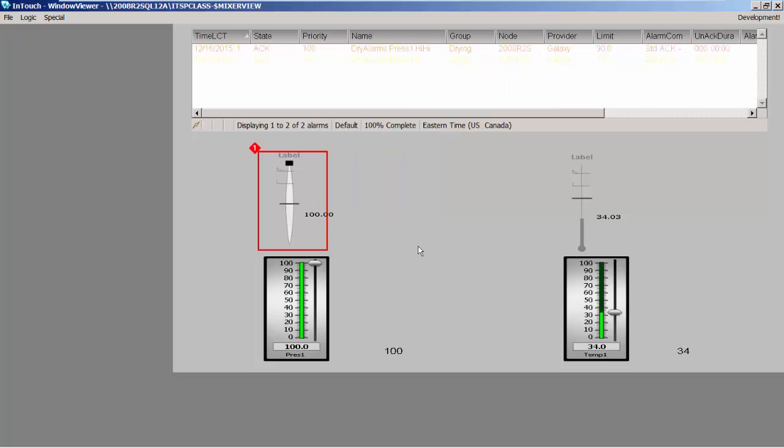And then you can see it stopped flashing, but it's showing me now that I still have an alarm, right? I still have an acknowledged alarm, this high alarm, in that current state. So it's going to look like this until you take it out of that alarm condition. So if I drag it out of that alarm condition, you can see it reverted back to the high alarm, and now I've taken away, the AlarmBorder goes away.